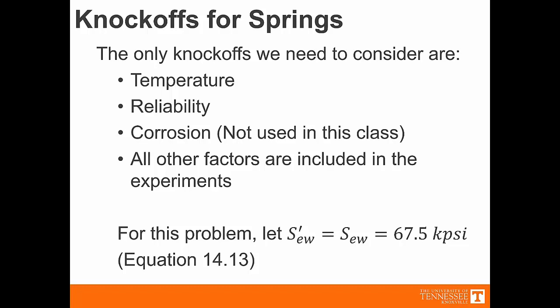Okay, so for this problem, we're going to let S_e' be equal to S_e, which is 67.5 kpsi. What that means is that we're taking all of these values to be 1. Our C temperature will be equal to 1, etc.